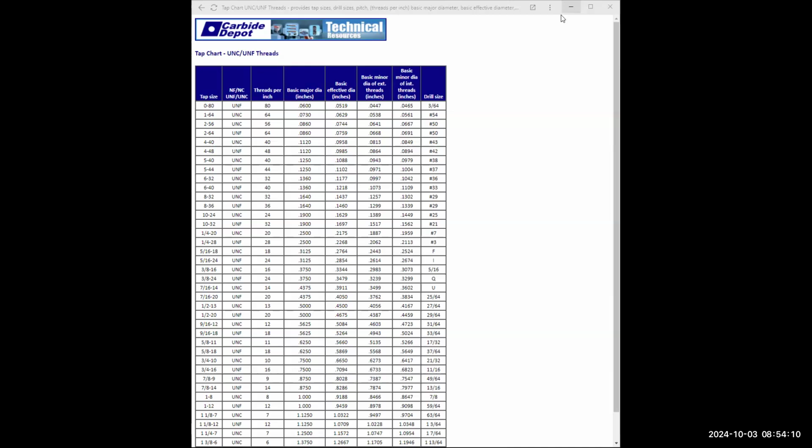Now, we want to type in P for property, and select line type here, and type in hidden. Enter, enter. Because you can't see those holes from the front view. The hidden lines indicate that there's a hole going all the way through the part, basically.